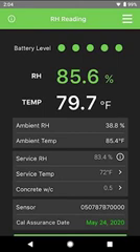When a new measurement is made, the reading screen displays not just the RH and temperature as read by the sensor, but also ambient RH and ambient temperature reading as read by the internal sensor embedded in the Total Reader device. Underneath the ambient readings is the service RH as estimated using the service temperature and concrete water to cement ratio as set using the icons directly to the right of these values. A service temperature of 72 degrees Fahrenheit and a cement to water ratio of 0.5 are quite common, but other values may be set.